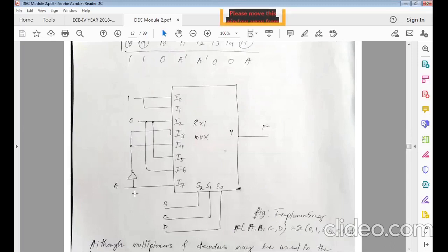So moving on, what we do now is we take these inputs and we put them across my mux. The same order is maintained from LHS to RHS. Whatever numbers are going from left to right, the same thing comes from top to bottom here. So this should be maintained. So I have 1, 1, 0. So 1, 1 is given, 0 is given to I2. I3 is A bar. A I have here going through an inverter, so I get A bar, right?